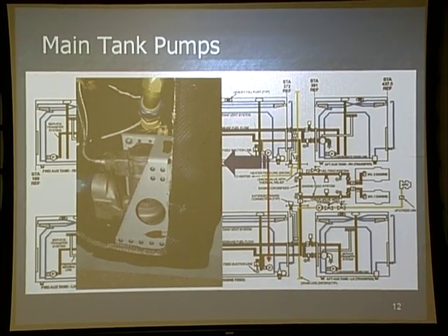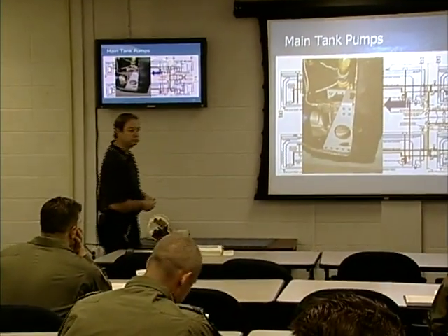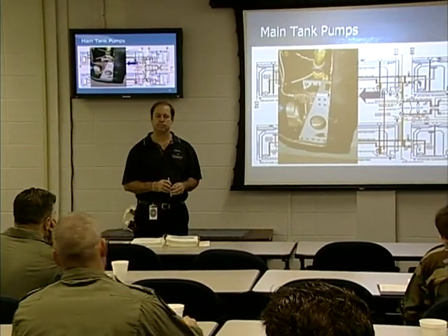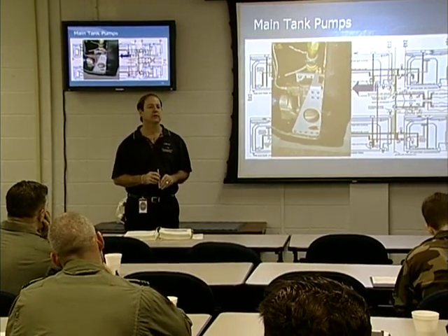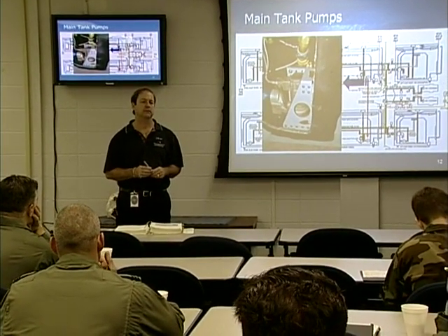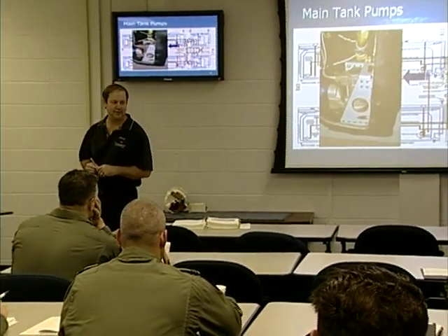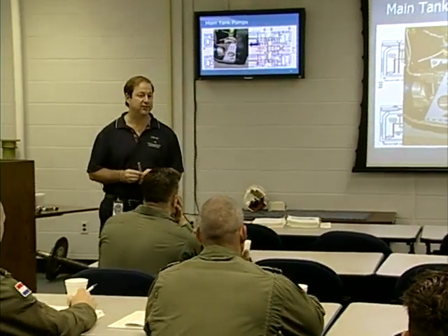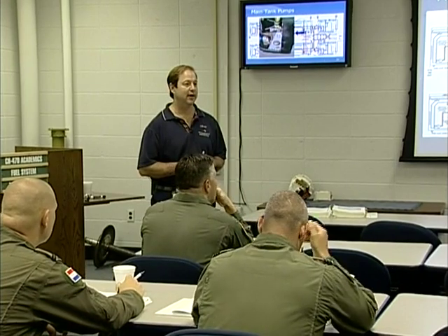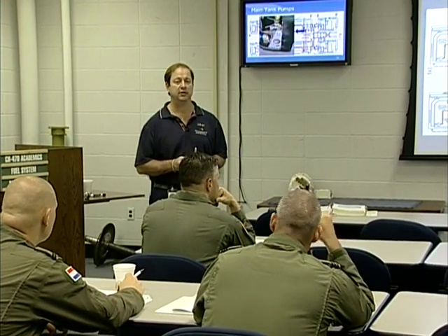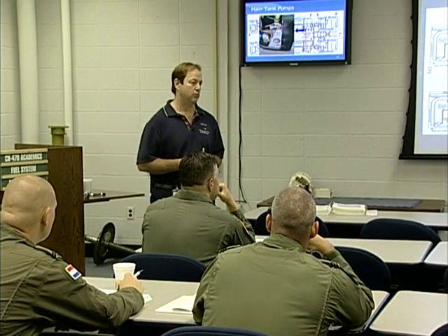Now, are the aux pumps required for flight? Yes. Anybody else? As long as you have fuel in the main tanks. No. Okay? It's kind of a trick question, gentlemen. If we need that fuel to get us to destination, then yeah, we need the pump. Okay? If we can get to destination without all the aux fuel, then no, you don't.